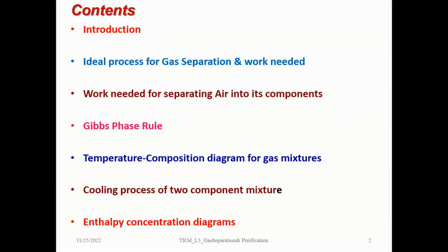Next, we discuss the Gibbs phase rule, which tells you how many independent thermodynamic parameters exist for either a single component mixture or multi-component mixture. The temperature composition diagrams for gas mixtures will be discussed thereafter. And we'll also see the cooling process for a two-component mixture, for example, nitrogen and oxygen, and its enthalpy concentration diagrams.